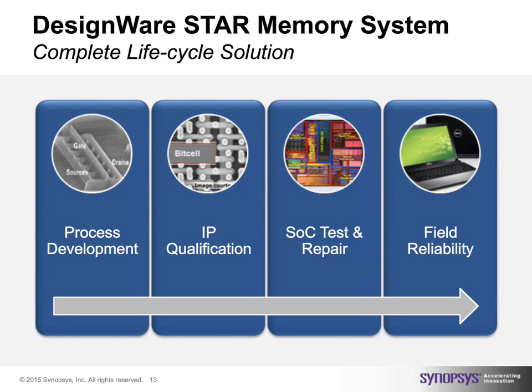Now, of course, SoC designers would use it as well to incorporate it in the design and also use it for analyzing the chip later on. That's the SoC test and repair advantage. And the field reliability, we're seeing more and more utilization of this solution, especially now with FinFET. We see various problems that would happen during the lifetime of the chip, whether they are soft errors, whether they are aging-related matters that would need the Star Memory System to be used later on systematically, either periodically, on power-on, self-test, self-repair techniques, as well as ECC-oriented online test and correction activities. And we'll talk a little bit about that also towards the end of this presentation.